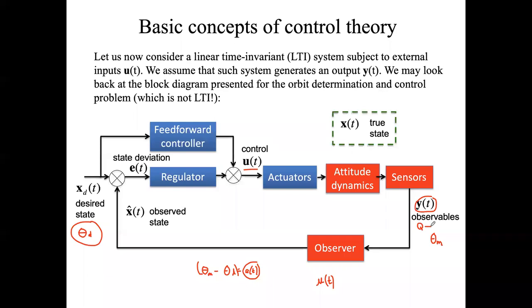You can transform the quaternion by using, if we're assuming small angle approximation, theta. So these will transform in theta, and this theta will be indeed our theta measured. The reason why you need to do that is because usually your desired attitude is in terms of angles. We are going to deal with angles because, for example, our desired goal is to have the desired pitch or yaw angle equal to 0.